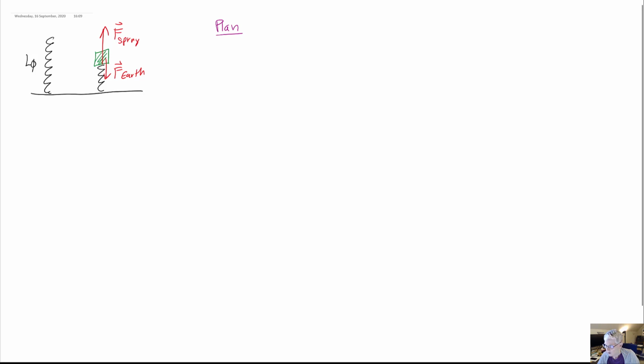And to do that, we're going to need the vector L, which points from the base of the spring, the fixed end of the spring, to the movable end. And we're going to need to get that by vector subtraction. It's basically equal to the position of the block relative to some origin minus the position of the base of the spring. And we can use this now to get the stretch of the spring.